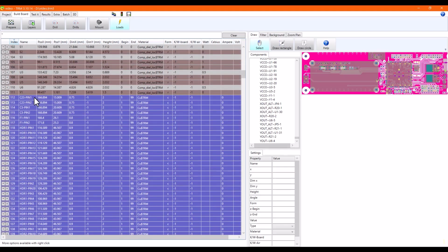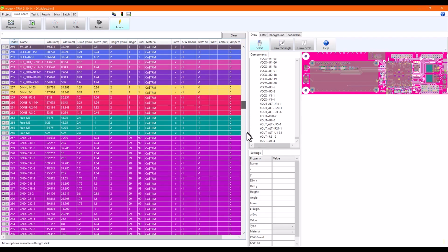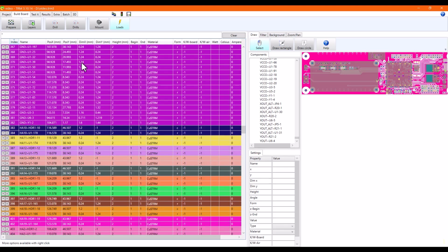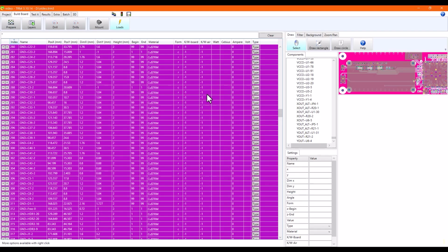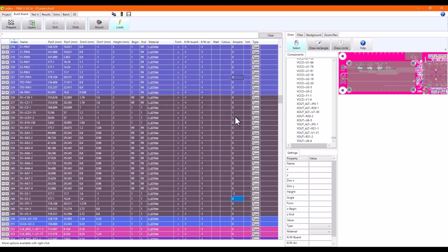Then we have a bunch of so-called pins. Those are the wires. Then we have a colorful table with representatives for the netlist. This object is number 39 of U1, and this pad is a member of the ground net. Here we see what we defined in the parameter list in Altium: plus 2 amp at LCD1 and negative 2 amp at a connector pad.